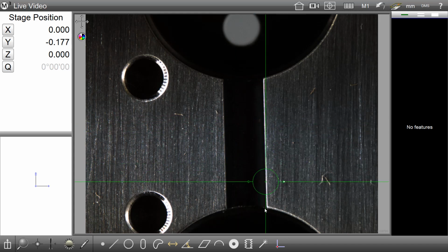One of the other differences you'll note about the Simple Active Crosshair in this mode is that the scan across the edge transition occurs directly along the line of the crosshair probe itself. You can note this by putting the probe into rotate mode and see the edge candidate position move along the edge directly along the horizontal scan line in this case. This should provide the user the ability to identify edges in a much more straightforward fashion without relying on the automatic edge detection capability supported in the Active Crosshair in the current M3 release.